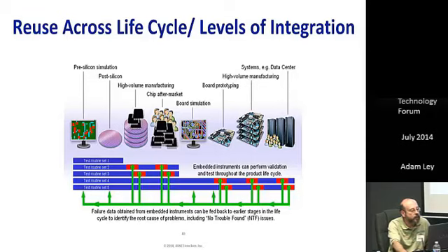The same instruments that are used on the chips, accessible through the JTAG port, are likewise accessible when your system is in the field, and you can take the information that you gather from those later phases of the life cycle and feed it back to improve your incoming quality as you progress through the life cycle.